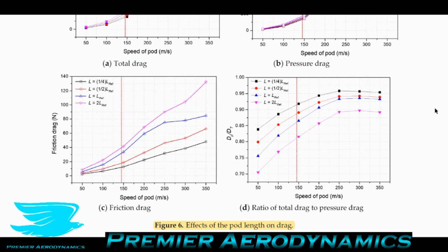And if you want to make your experiments better, so you're in aerodynamics and you're doing experiments, or you have your CFD and you need experimental data to validate your CFD, make sure to measure the density of the air in your system. We've talked about it in this paper, how the density of air can change, and it does change on a regular day by 2 to 4%. As I'm sure you're aware, we made a podcast about it, podcast number 54, and it shows how the changes in the density affect the flow physics and forces on bluff bodies and streamlined bodies.